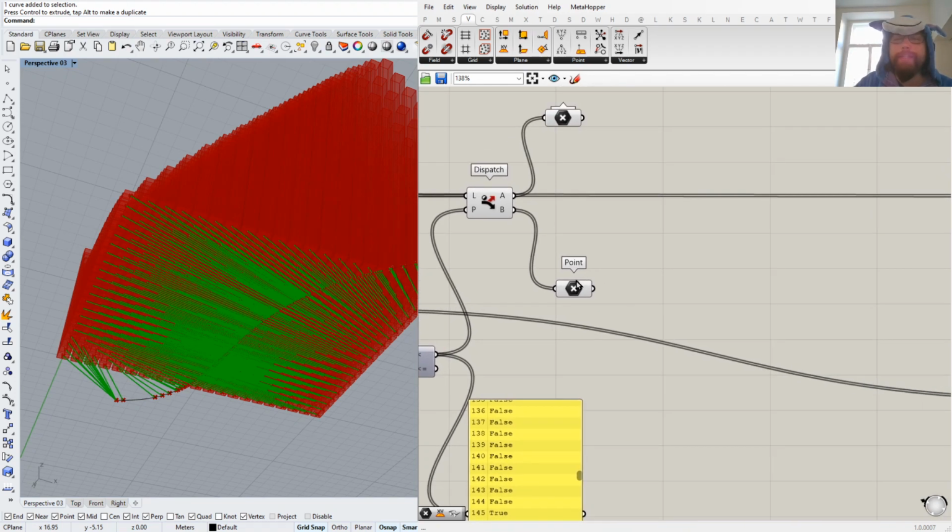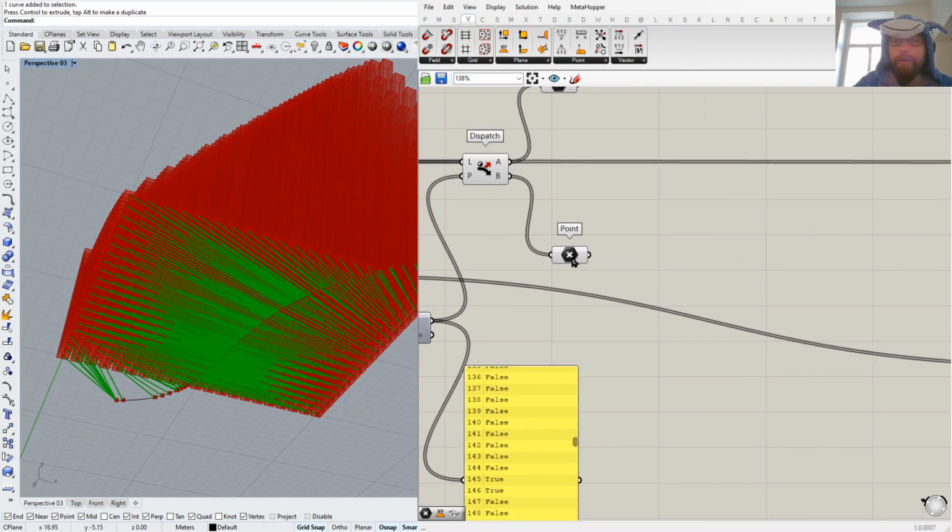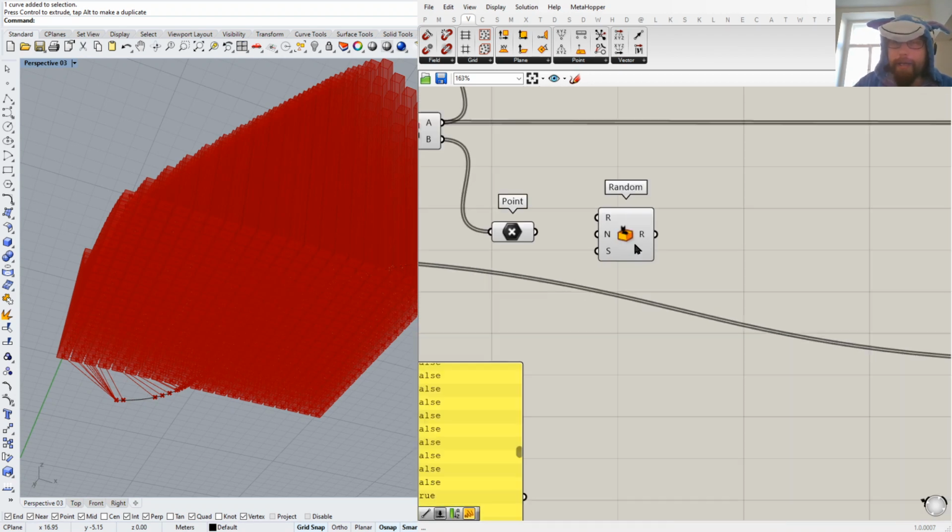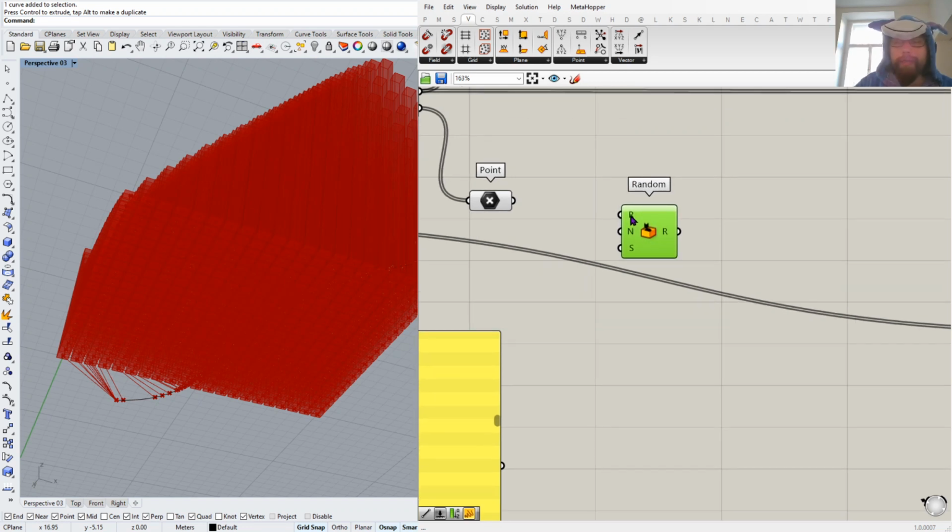Let's do pure randomness, and then we can try to improve this. So these points need to move randomly. So I just create a random number, and this is a new component. So let's look at it. What does it want? Range is the domain of where the numbers belong. From 0 to 1 is kind of good, but in this case, I want from -1. So I'm going to type it exactly, -1 capital T-O +1. So this is going to be my range.